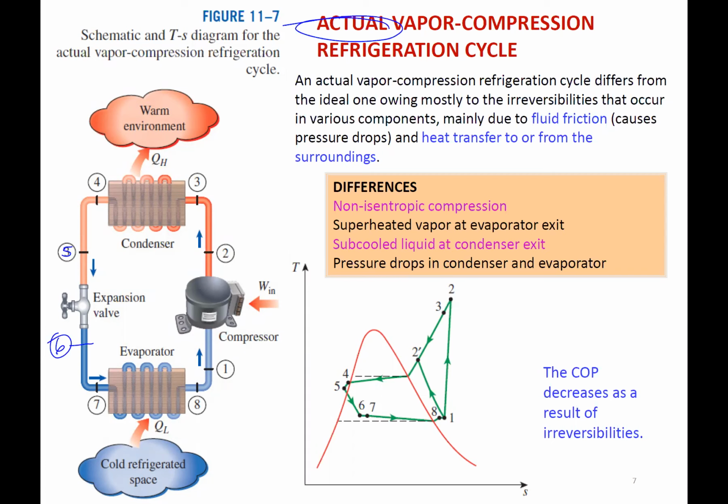So you see all these different states, and that's because they're breaking up this pipe section: 2 to 3, 4 to 5, 6 to 7, 8 to 1. Okay, they can have heat transfer going on between those and pressure loss due to friction between those, so that you get this change between those states. Okay, because you've got to connect those components together, and they might be a long pipe and things happening at those points.